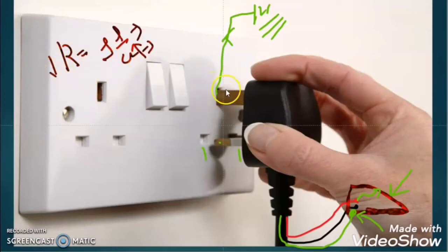So if we make the cross section area of the earthing pin high, then the resistance of the earthing point will be low, which is good for the earthing. The lower the resistance for the earthing, the better it is for the electrical installation. So this is the second reason for making the earthing pin thicker compared to the phase pin and neutral pin.